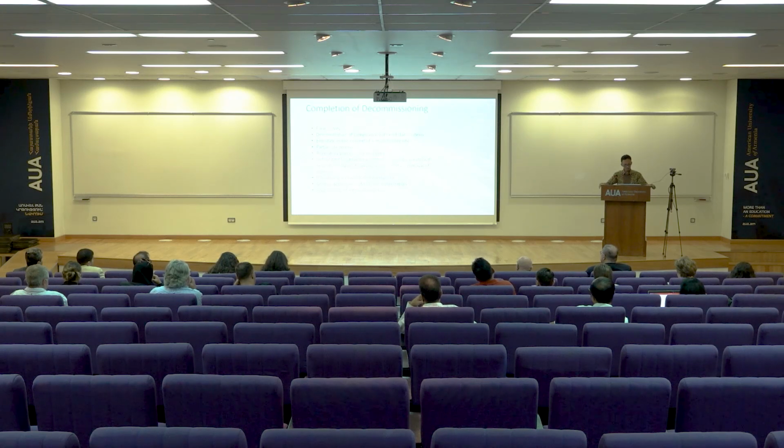And then the final step, the completion of decommissioning: we conduct a final survey, demonstration of compliance with end state criteria, end state in context of multi-facility site, partial site release, regulatory process and decision, definition of institutional control in case of release restriction, introduce new practice on site, graded approach, justification, optimization, and also involvement of interested parties.